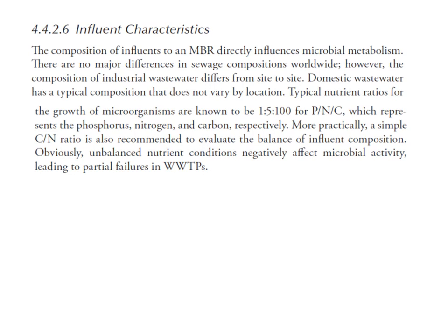A typical feed solution should have the ideal ratio for phosphorus, nitrogen, and carbon, and this ideal ratio equals 1:5:100. That's something that these living microorganisms need for making their cell body. Obviously, unbalanced nutrient concentration negatively affects microbial activity, leading to partial failure in wastewater treatment.